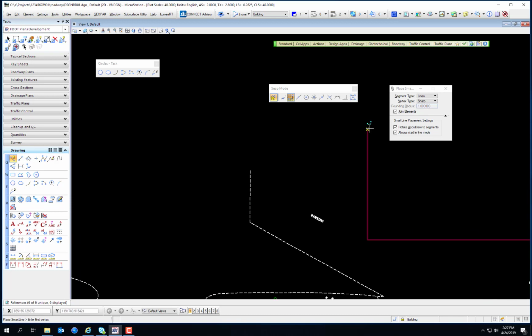We also mentioned tentative snap. A tentative snap is sort of the old school way of doing things. AccuSnap gives you a little yellow snap that says, yes, you're about to draw from that point. And you just click, and there you go. It's a floating tentative. But you see how it's a little dotted plus sign there? If I hold down the 2-button chord that I mentioned before, it makes a much larger solid plus, and that is my tentative snap. I have not executed the tool. I have said tentatively that's where I want to snap to, and it says this is a key point.